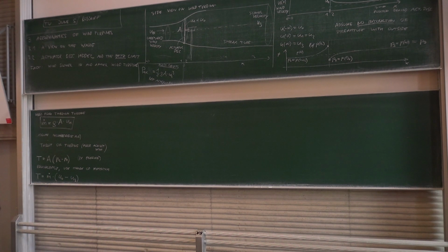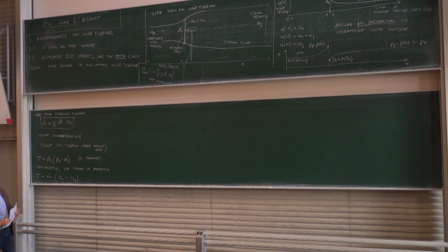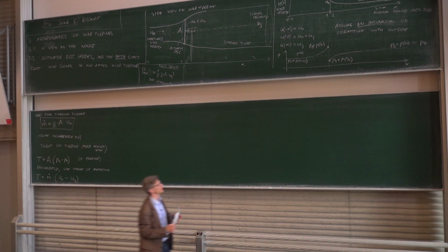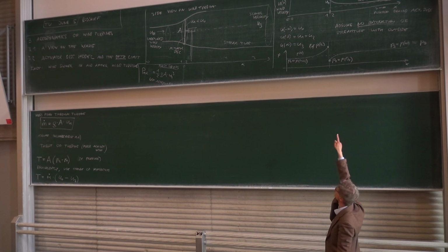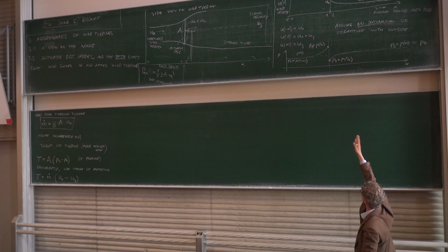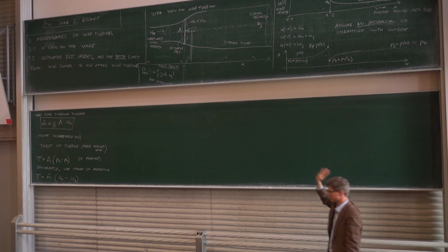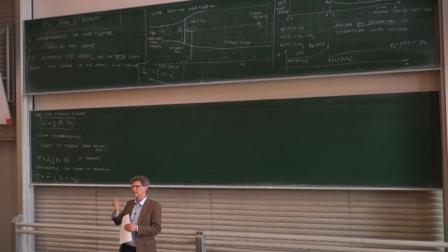So at the end it will have another speed. And this whole speed change will of course be caused by the pressure differences here. If we look at this picture here, I would like you to get the picture. The air gets already slowed down before it arrives at the turbine, and that's due to this negative pressure gradient here. Right? It's pushing basically in that direction. And then the same thing happens even after the turbine. It gets also slowed down. And at the turbine itself, there's this change where the airflow doesn't interact only with other air, but it interacts with the disk itself, and that's why this discontinuity is possible.